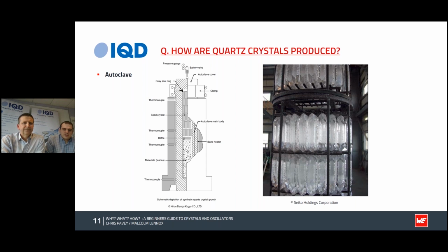The temperature difference controls not only the supersaturation in the growth chamber, but together with a baffle, controls the rate of fluid and heat transfer between the two chambers. Growing temperature also has a strong effect, with the growth rates increasing and decreasing with temperature.